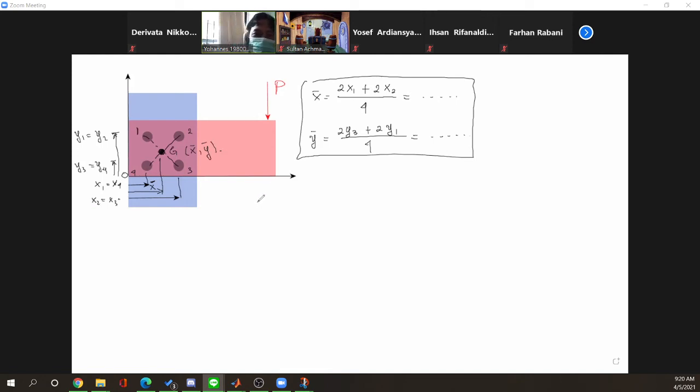So while we calculate the center of this joint is to measure the eccentricity. Okay, so this is the eccentricity. Because we have eccentricity here, this load can create moments or torsion load on this joint.